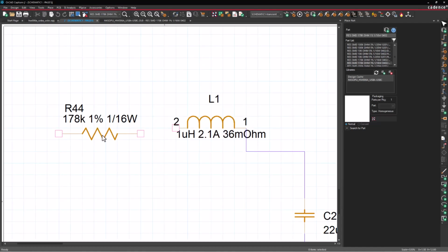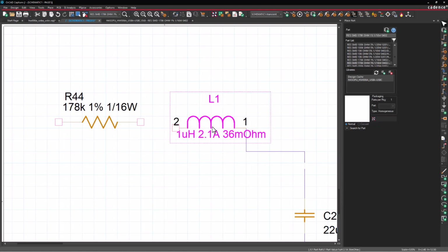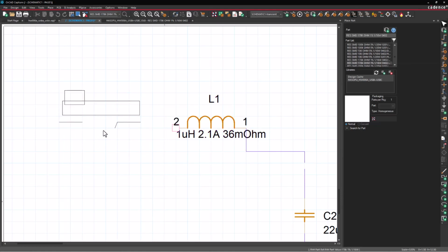So, whenever you see pins placed off grid or on half grid, or something that's not the standard, you'll get this problem where most of your components align with the grid quite nicely once you pull them out of the library, but one part or a few parts just do not align. They align in the middle of the grid. I would not recommend changing your entire grid just to accommodate parts.